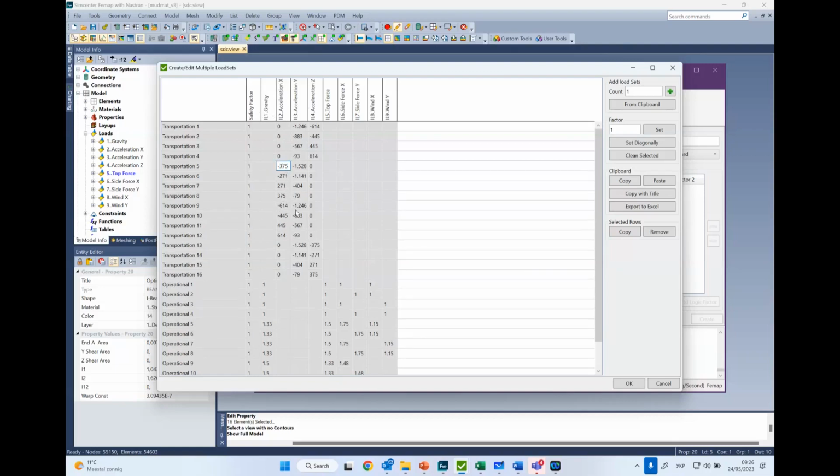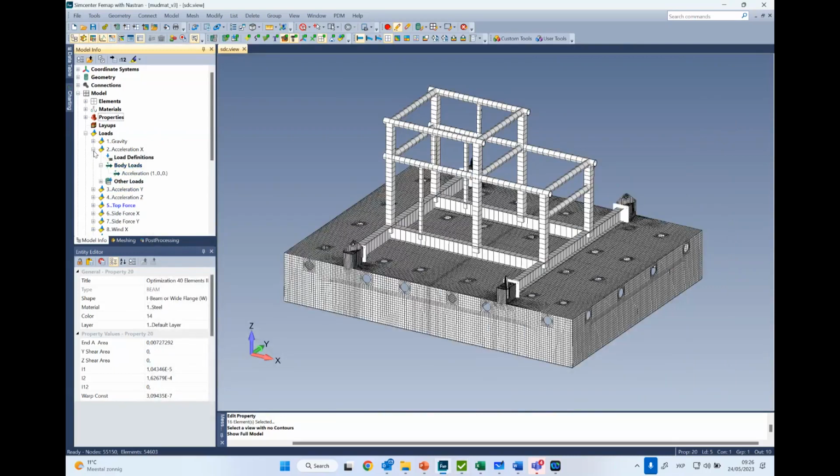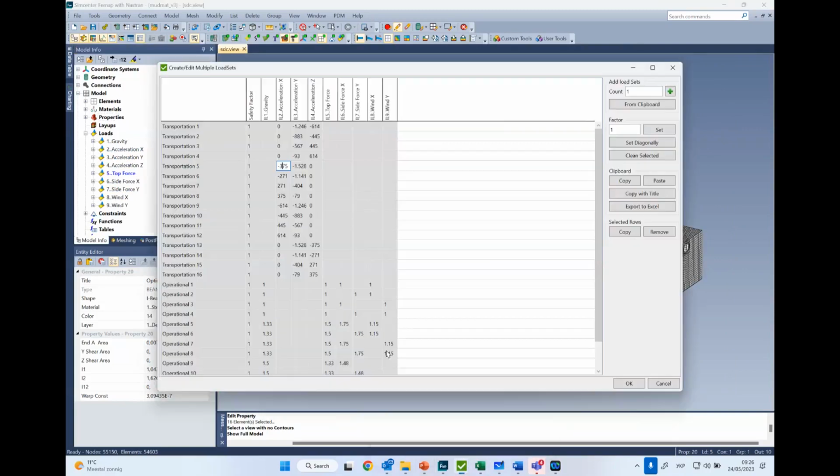I think here it was supposed to be the dot on this factor because we applied the unit load in FEMAP. So we have x, y, and z acceleration of 1 meter per square second, and then we just multiply it with the different factors. But I'm pretty sure that this result won't be very representative, since it has to be the dots.